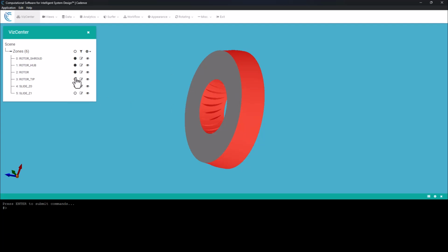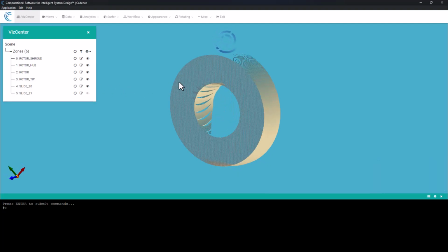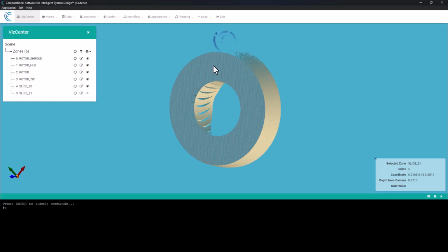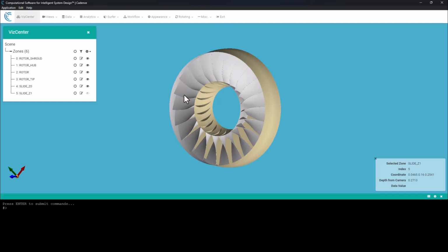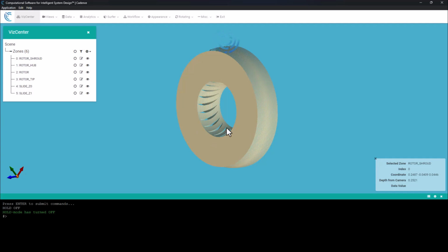And you can see here that they are silver, but we want it to be gold so that it's fluid touching inside it. So if I hide this one here, you can see what's happening inside. It has to be gold all outside and then silver inside. So we have to flip the normals for the interfaces here, which is what the script is doing. So to proceed in the input file, I'm going to click hold off for it to do the flipping. And once the normals have been flipped, you can see that everything is gold outside, which is what we want in this case.